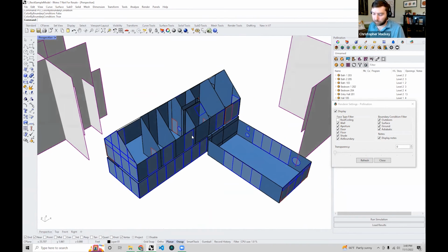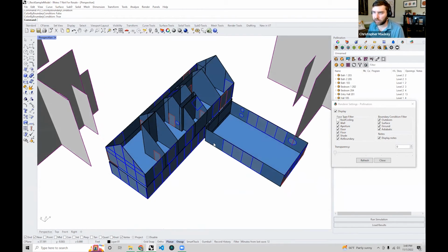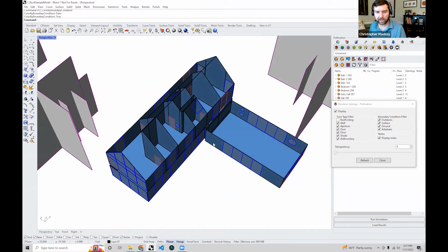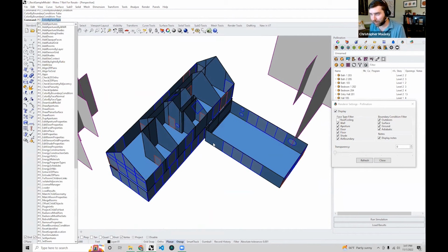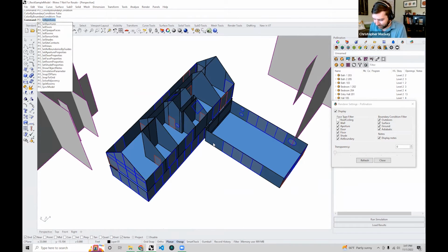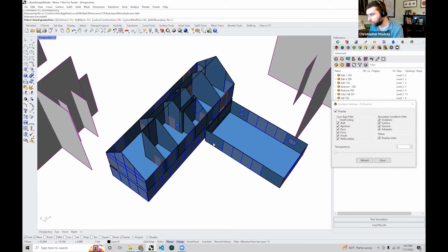So very clearly, what do we use to make sure that we assign correct indoor boundary conditions in the previous model? What was the name of the command? Do you remember it? It's also the same name as a Grasshopper component, PO solve adjacency. Yes. Okay. So that's what we're going to use right now, to basically set everything to be an indoor boundary condition, or automatically do this intersection and figure out stuff for us. So I'll hit solve adjacency.